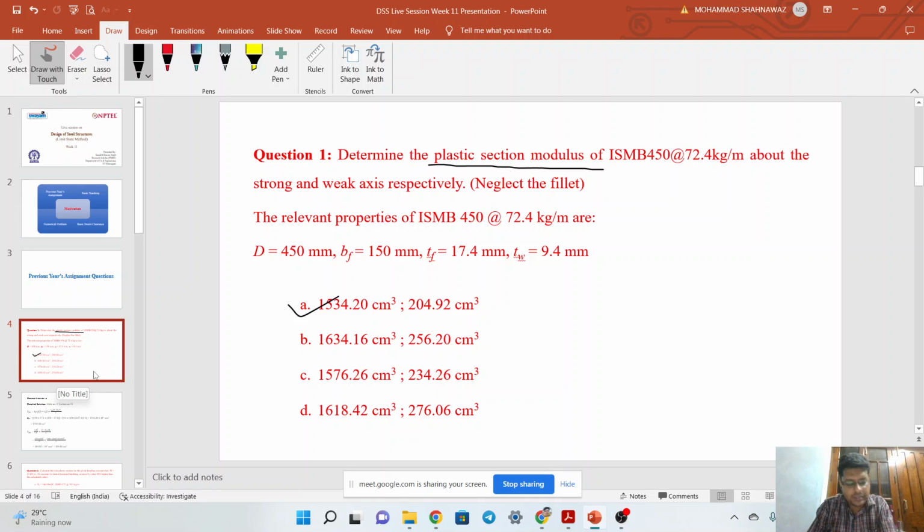We were calculating the web buckling strength. In the video on web buckling strength, we had the formula B plus 2 N1 into thickness of the web into FCD. For the calculation of FCD, we require the slenderness ratio, and that slenderness ratio was given with the effective length as 0.7 upon radius of gyration. Can you share your doubt on this screen?